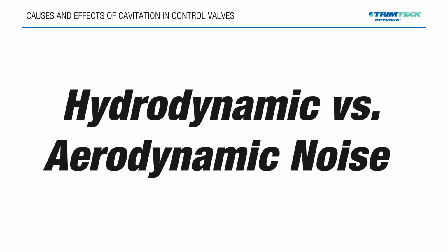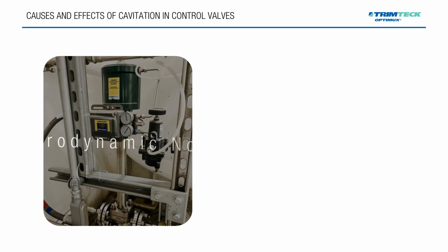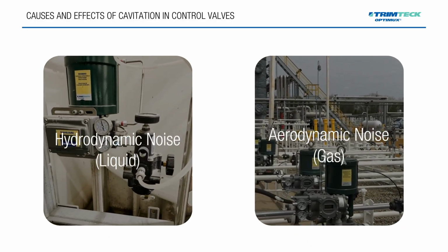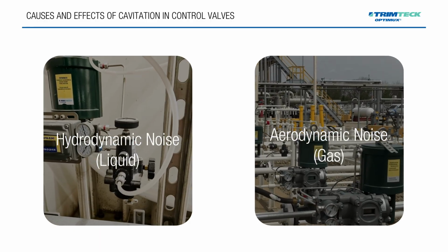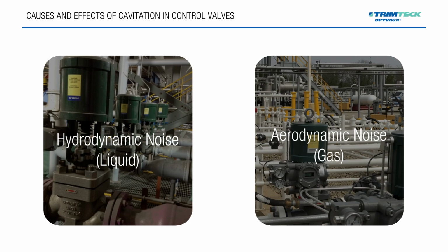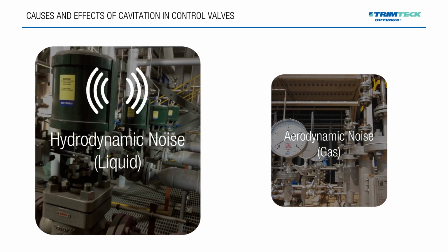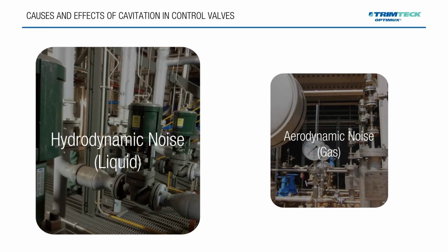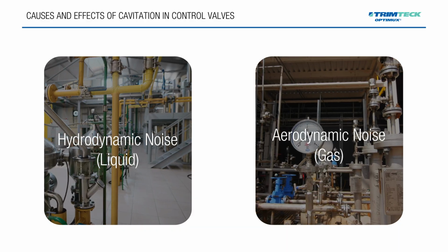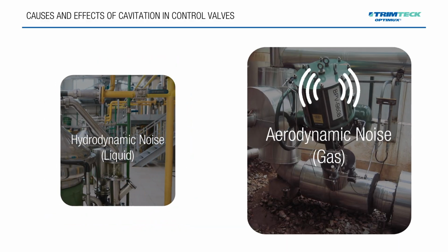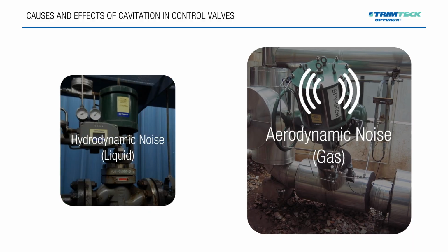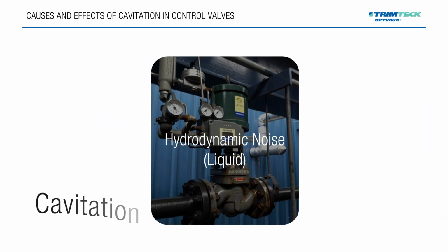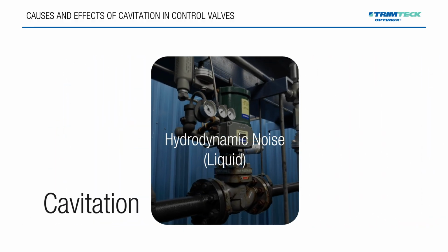Hydrodynamic versus aerodynamic noise. Both cavitation and flashing create hydrodynamic noise. That's noise generated by collapsing bubbles in liquids. It is often compared to the sound of gravel or marbles tumbling down the pipe. In contrast, aerodynamic noise comes from turbulence in gas or vapor service. We'll explore that topic in another video. For now, we'll focus on cavitation and its effects in liquid control valves.